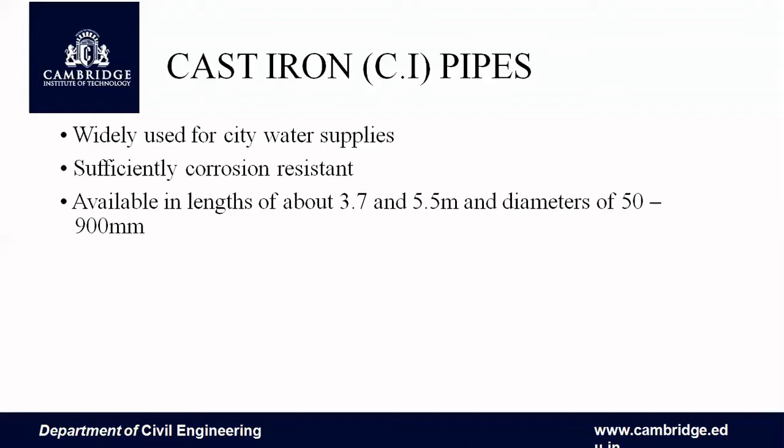And the disadvantages. The interior of the pipe becomes rough as time passes, as years pass, so the discharge carrying capacity will be reduced. And if we use larger diameter pipes, they are heavy and also uneconomical, and they will break during transportation as well as during the joining.